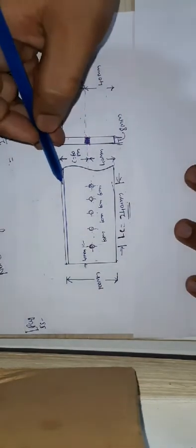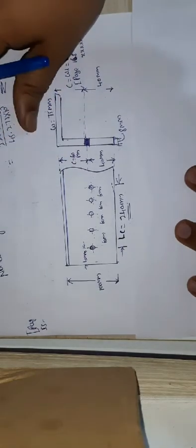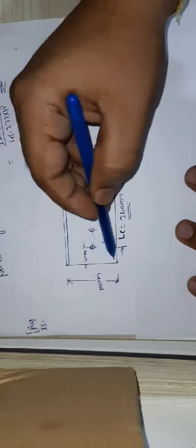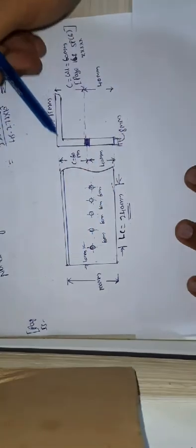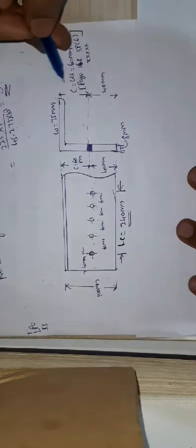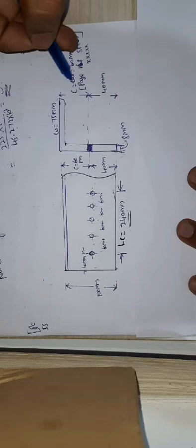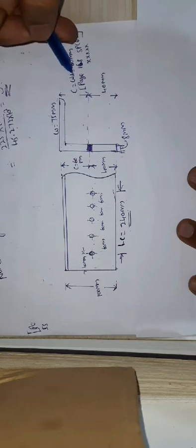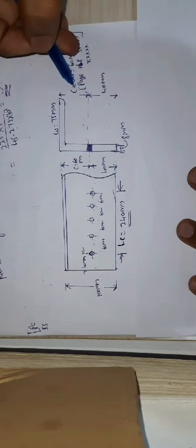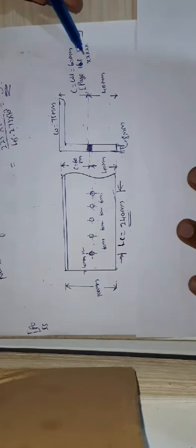Then here I drew the connection of the single angle section. Here is the pictorial representation. You can see the length of the connecting leg and the length of the outstanding leg, and here there is a C value. What is that C value or WL? We'll come to know this terminology afterwards. C is taken as WL, that is 60 mm, taken from page number 168 of SP6.